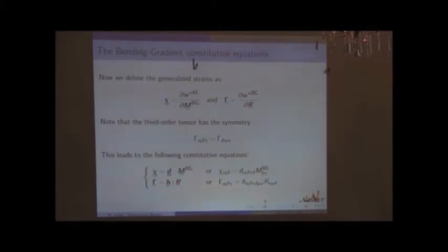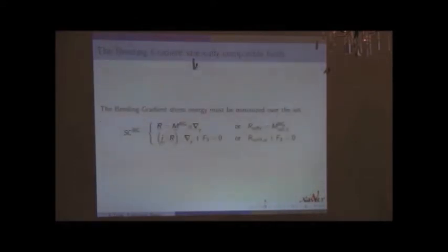With indices, this is starting to be a bit cumbersome. Monoclinic symmetry, I said that. When I computed the energy, you don't have coupling between those because transverse shear is uncoupled from in-plane stress and Poisson effect because of monoclinic symmetry.